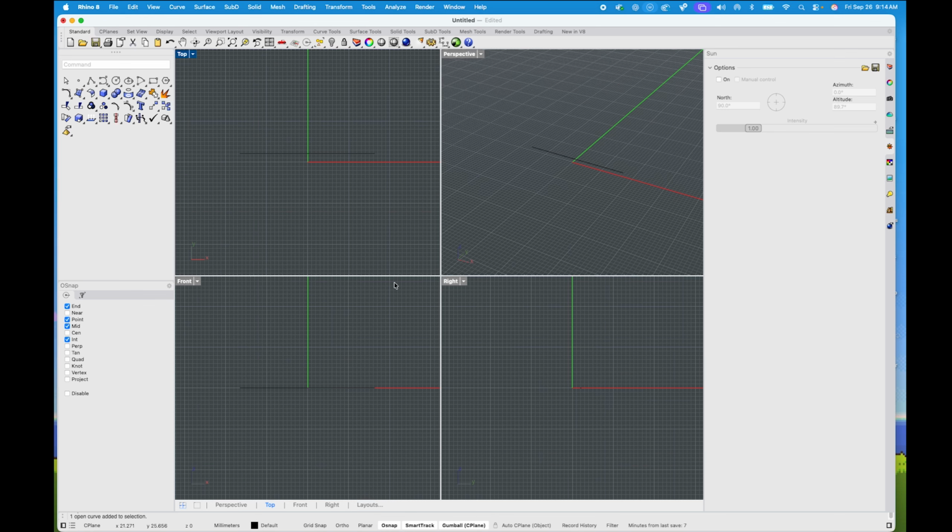Now, funny enough, each of you has three of those sides, or three of those viewports, if you will, of an object. The screen is actually already displaying this in real time. So for instance, if I type in box, enter, and I can even set coordinates such as 0, 0, x-axis 0, y-axis 0, you'll see that it locks on to our origin point. Eventually, I can make a box.